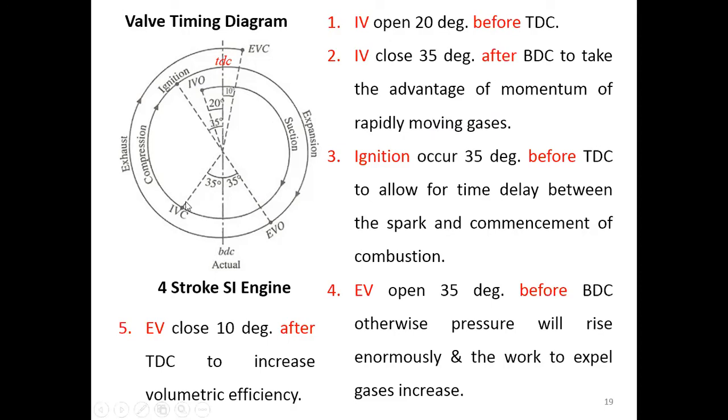Okay, and then after the inlet valve closes, compression happens, right? And ignition takes place here. From the valve timing diagram, the ignition occurs at 35 degrees before the top dead center.